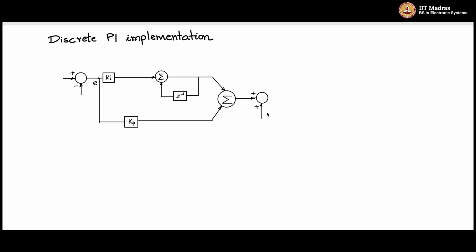Then together the small signal plus the steady state value will form the control input, which can go to the plant, but you may have to pass it through a limiter first so that whatever value you get here does not exceed the extreme limits, Vmax and Vmin. So this will be Vmin, let's say this is Vmax, so this is a limiter.